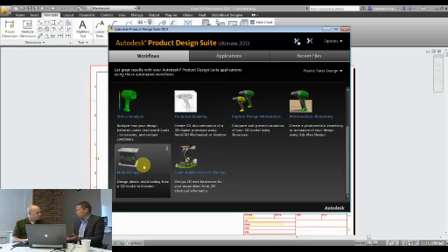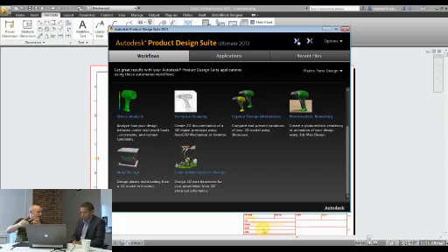It could be that you have control systems for maybe a consumer product with electrical wiring. Now, the product design suite includes AutoCAD Electrical to enable you to create your schematic 2D electrical designs. There's also a workflow here with the Launchpad to take that information out of the 2D electrical environment and bring it into a 3D model, so you end up with that complete product. So if you were designing this mouse that I have here, you could do the mold design, and the die for actually punching this thing out, as well as the electronics on the inside.